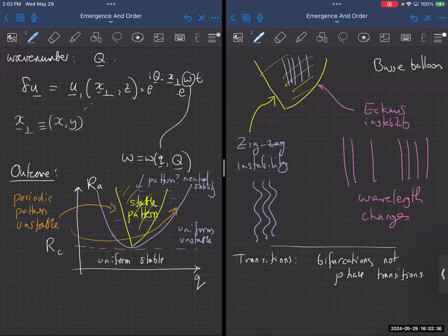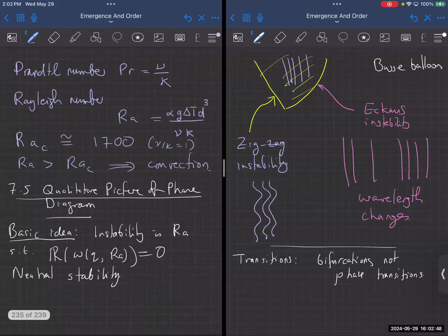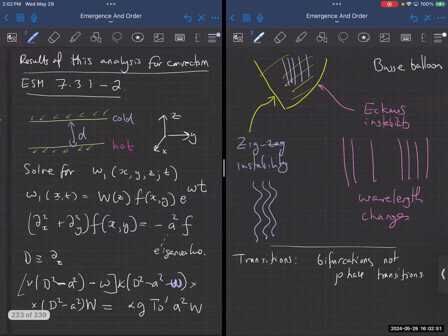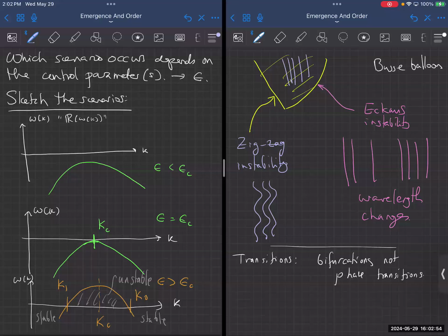This is really where it gets bizarre. If you look very close to the laminar-turbulence transition in a pipe, just like in today's lecture, where we saw that there is one mode that just becomes critical, you look at what the critical modes are. And what you see is that there are modes that are turbulent, and there's one mode going around the pipe in the azimuthal direction, and that mode is an emergent mode generated by the turbulence.